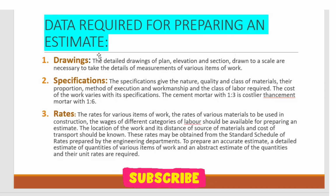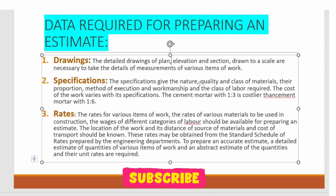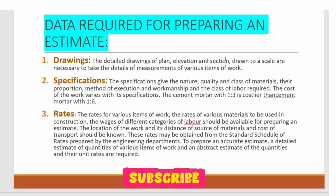So here we are listing, first thing is drawing, because once you have a detailed drawing plan, you can take necessary details or measurements of various items of work. Because without a plan, we cannot calculate the estimate. Again, to calculate the estimate, there are certain methods: long wall, short wall method, center line method, various methods are there. And for estimating the quantities, we need the drawing plan, because without a drawing plan, we cannot go further.